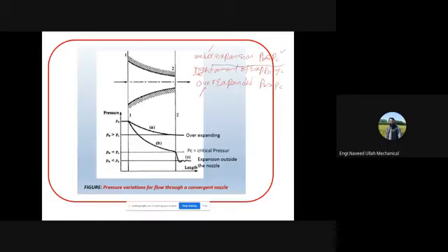We have discussed this earlier. And if the pressure at this exit, that is the design pressure, is equal to PB, that is the atmospheric pressure, you will have total expansion inside the nozzle, and you can get your required mass flow rate and your required velocity. And these are the off design conditions, when the back pressure PB is less or greater.